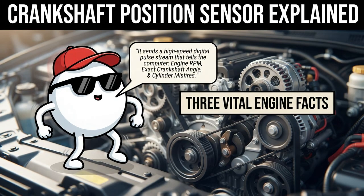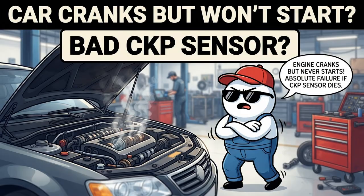It sends a high-speed digital pulse stream that tells the computer three critical facts: engine RPM, exact crankshaft rotational angle, and individual cylinder misfire events by tracking tiny microsecond variations in crankshaft acceleration. If the CKP sensor fails completely, the result is absolute. The engine will crank indefinitely but will never start.